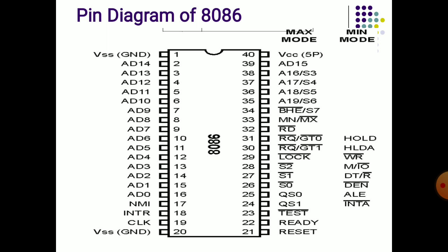And also, this 8086 microprocessor will support multiprocessor operation. What is multiprocessor support? The name itself says it. Multiprocessor support means we can interface additional processors to the main CPU. Here the main CPU is the master, and the other CPUs act as slaves. For example, complex mathematical operations cannot be done using a normal single processor mode, so for that purpose we need an additional processor. For example, we can take the 8087, which is a math coprocessor.